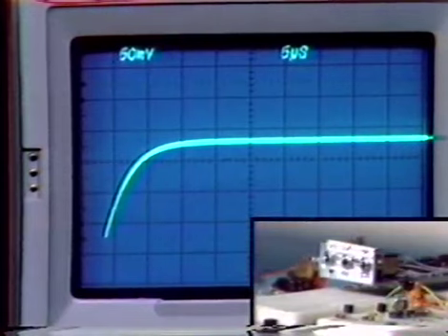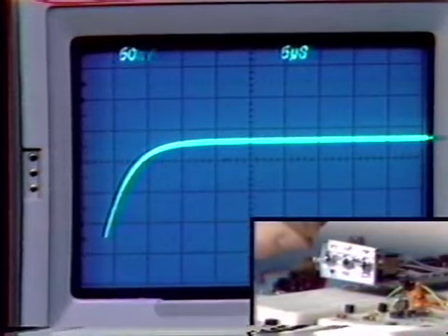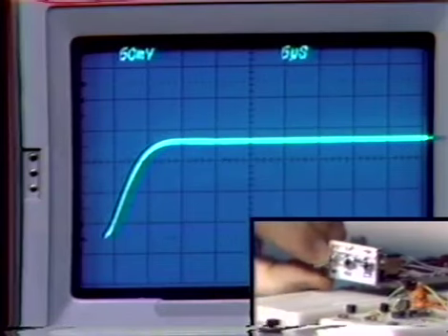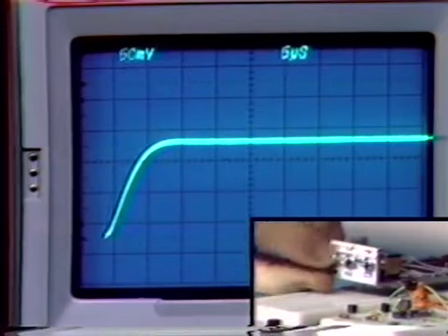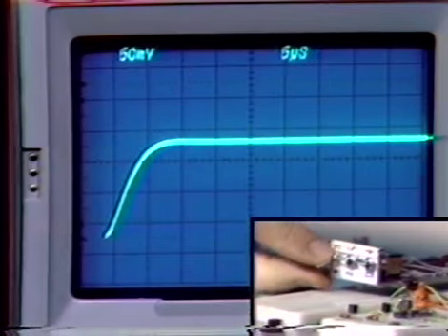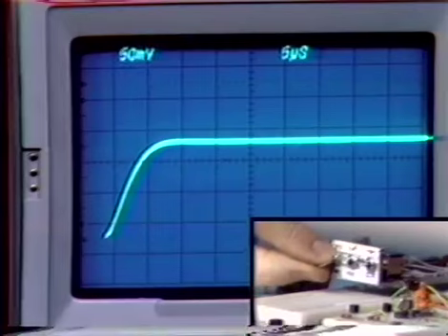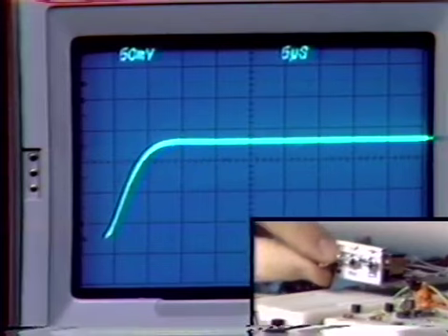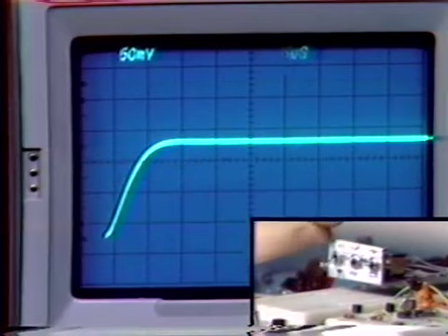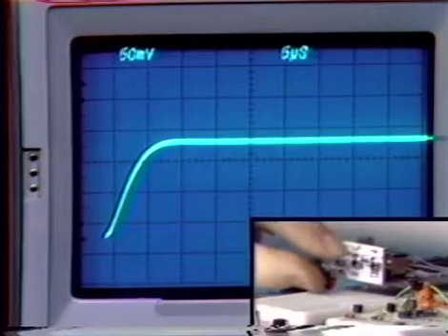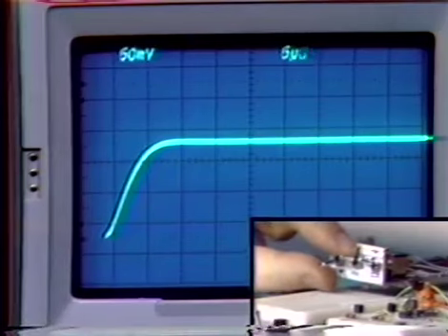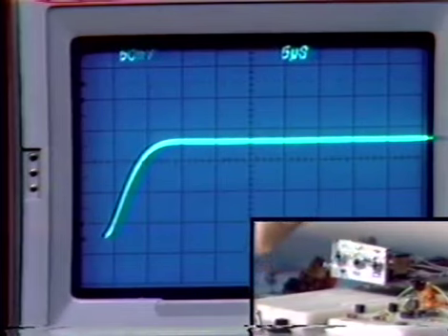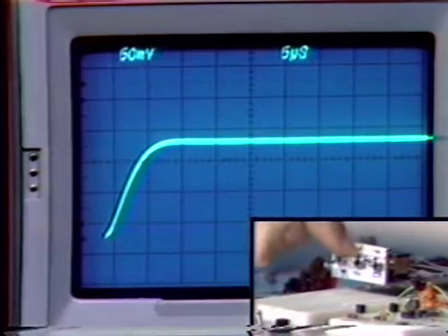Now let's begin to add additional poles. Let me start out putting in a pole at a megahertz. Well, that doesn't really have much effect on the response. So here's a pole going in at a megahertz. That's actually beyond crossover in this loop, and so there's very little change in the response. We see just a hint of overshoot, but really nothing very dramatic. Let me move the additional pole back to 100 kilohertz by appropriate choice of the R1, C1 product. I do that by throwing this middle switch down.